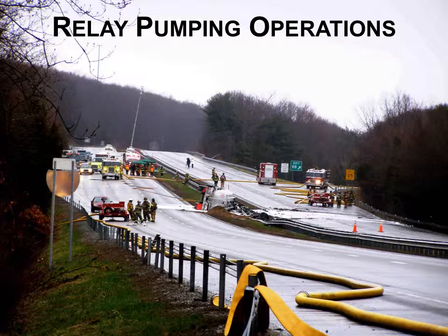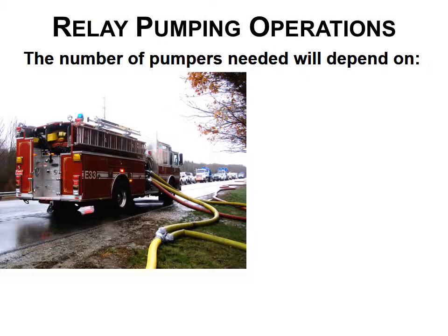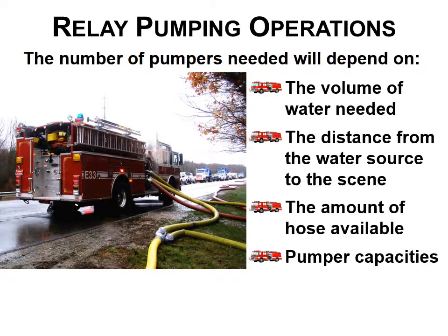Relay pumping operations: multiple pumpers can be used in a series to relay water to the scene if the water source is not close enough. The water supply must be capable of maintaining the required volume for the incident's duration. The number of pumpers needed will depend on the volume of water needed, the distance from the water source to the scene, the amount of hose available, and the pumper capacities.